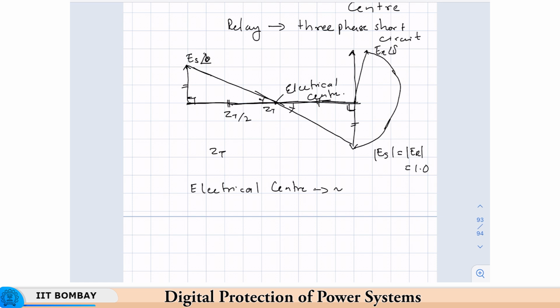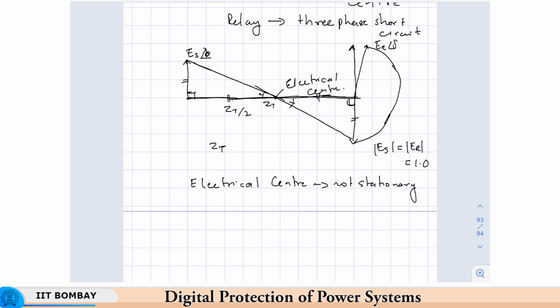It will appear, and if no relays trip, and somehow you are able to hold the generators, this will never happen, but assume for a minute that no action is taken and this swing continues, then it can reappear after one period of the swing frequency. Okay. So, the first aspect is it is not stationary.